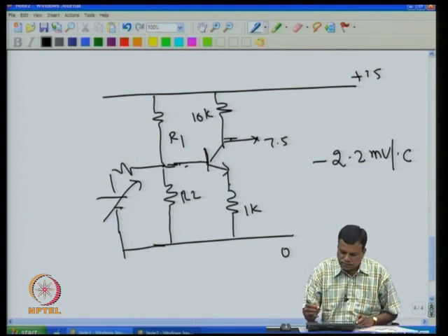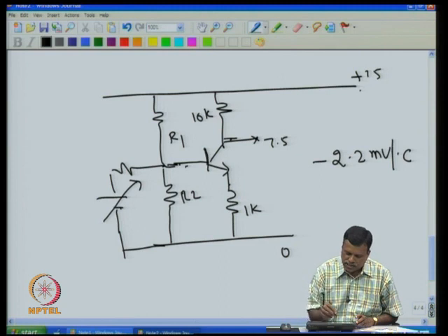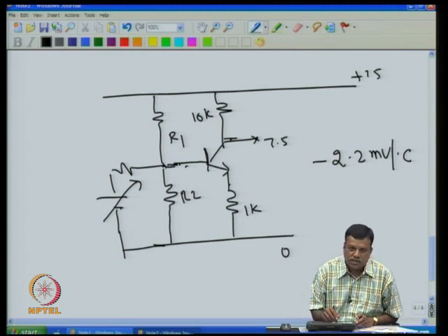That means even if this supply voltage is constant, even if this base voltage is constant, for example at a temperature of 25 degrees C, if the base emitter voltage is 0.6 and this is sitting at 1.35, you will get this as 0.75.